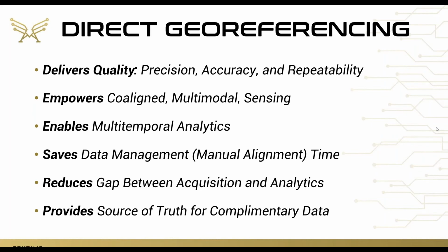Well, first, obviously, it provides quality. That's precision, that's accuracy, and it's repeatability over time, back to the points in the slides earlier. It empowers co-line multimodal sensing. So to Evan's point around how we do calibrations, how we do bore site calibrations, and how we bring that data together, it allows us to fly 3 very complex systems and align that data to a high degree of accuracy. So therefore, it enables multi-temporal analytics, which is critical to many environmental and agricultural or natural resources applications.